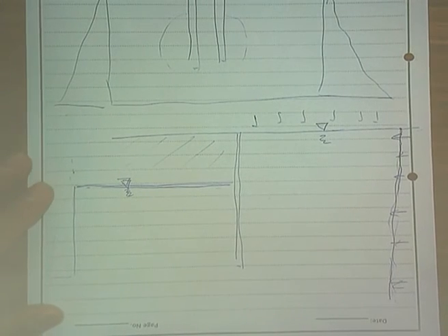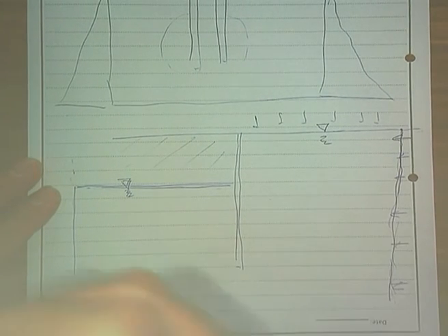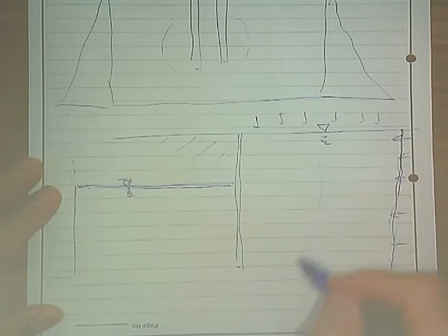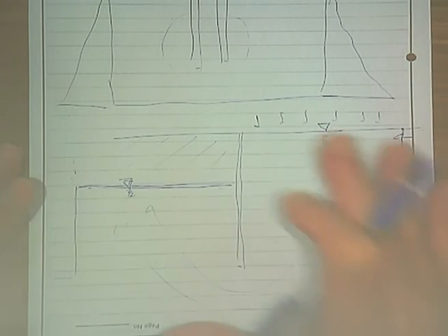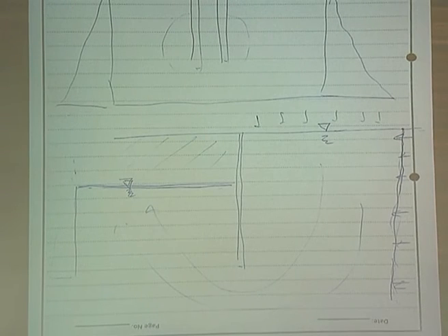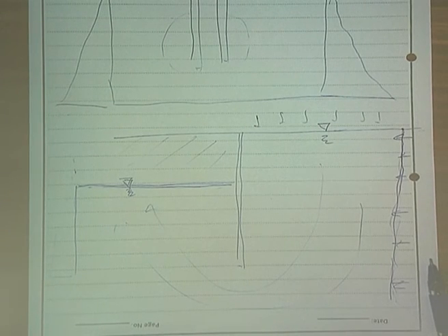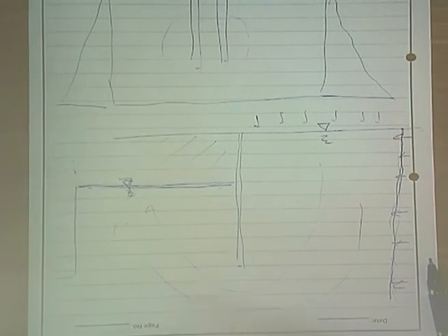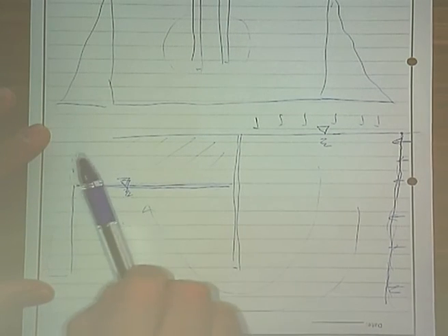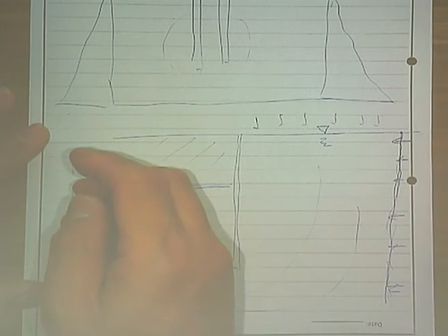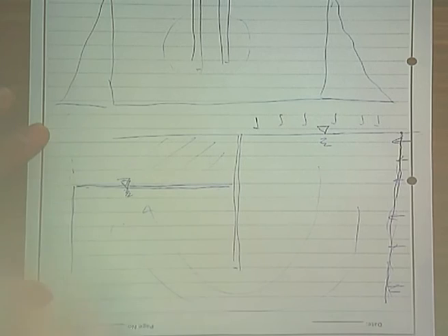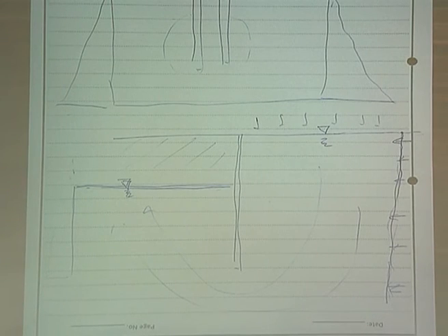Now, if you then run a seepage analysis, which Plaxis allows you to do, you will be able to see the seepage flow net coming through. And then everywhere the pore pressure will be defined by this seepage situation. So what you're saying is that after a very long time, if you keep pumping water from inside the excavation, you will set up a steady state seepage situation in which water will be flowing from behind the excavation to the front, to the excavation itself.